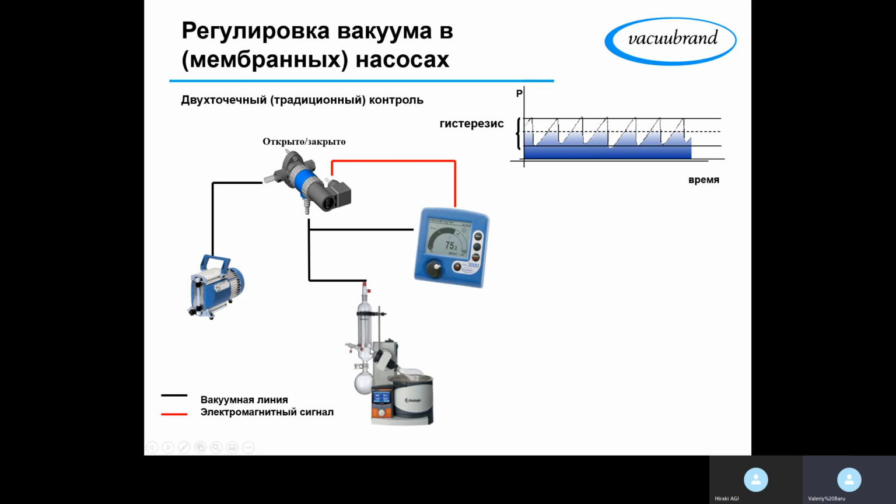So when we are distilling, we need to always take a look at the condenser and see that the amount of vapors condensing on the spiral of the condenser, in case we have a spiral condenser, is at the height of 2/3 of the height of the spiral. That's the rule of thumb which I mentioned, but if I got your question rightly, you are asking about the surface of the condenser, right?